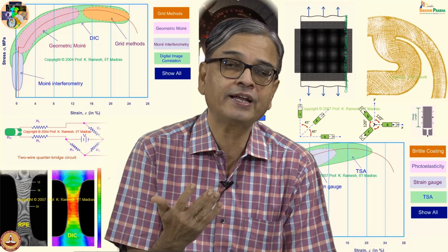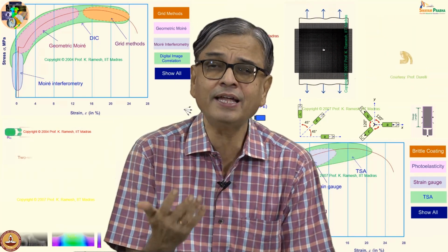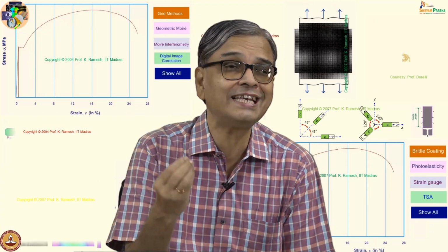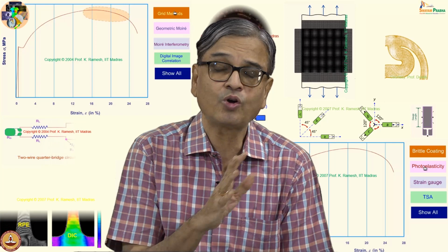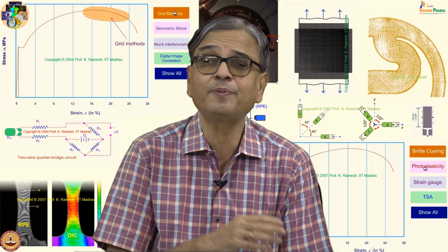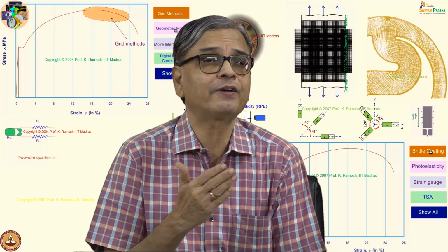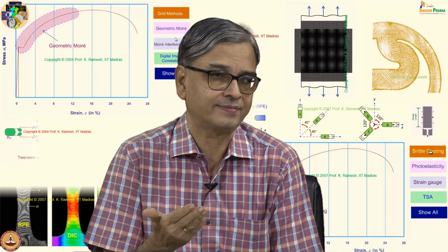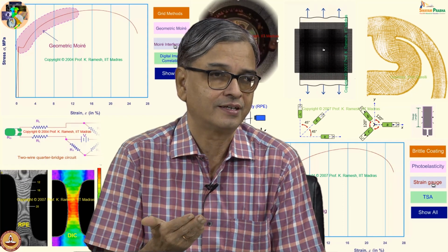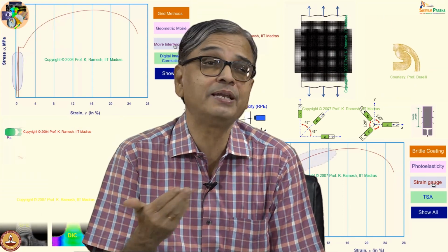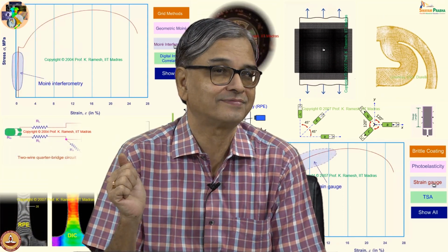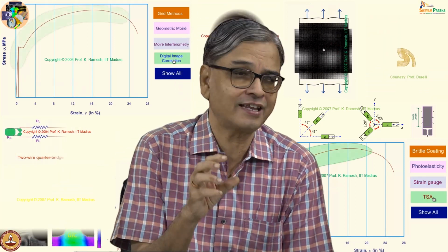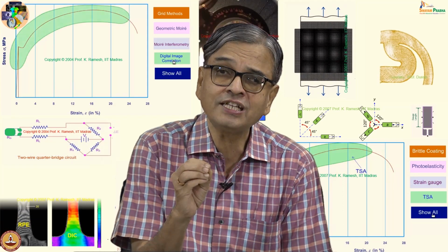What is the other way of doing it? You know, resistance is rho L by A. So, the other way of doing it is reduce the cross section to the least possible. With all those calculations, people have found, even if I want to have 100 ohms as the base resistance, I need about 100 millimeter length of the wire to do it. Because if I have higher and higher resistances, any small change I can make the measurement.